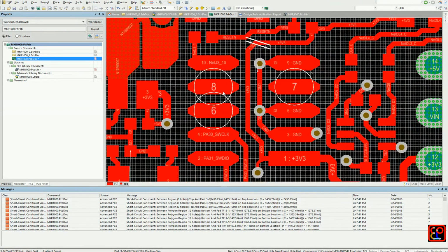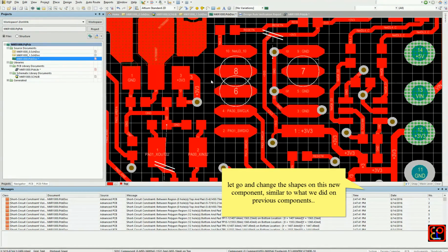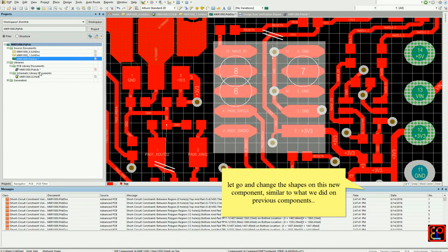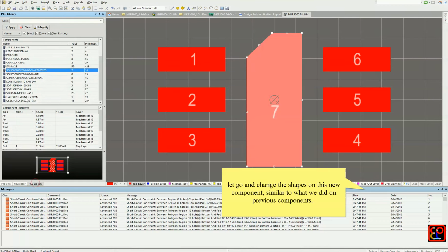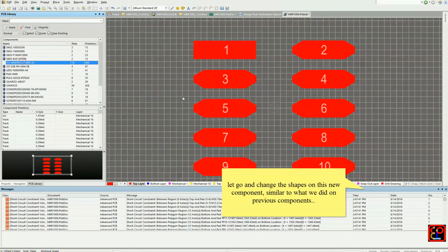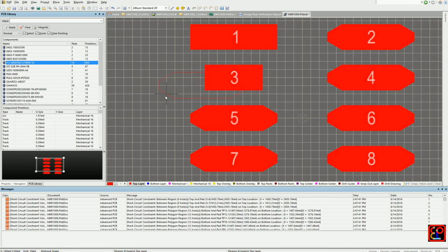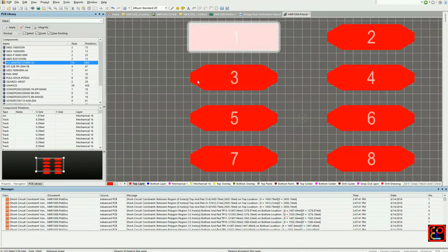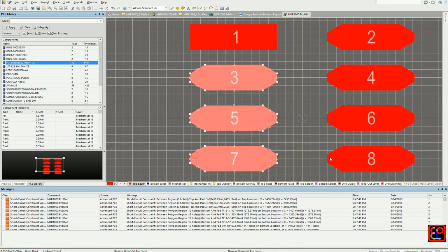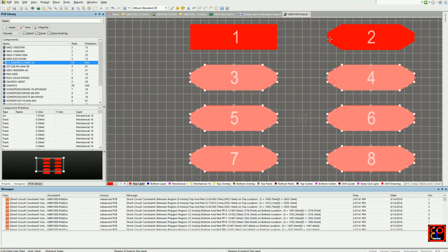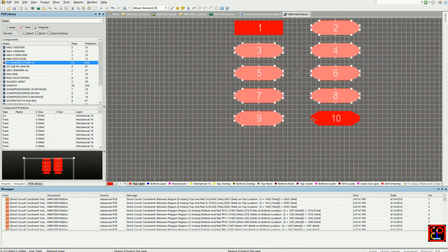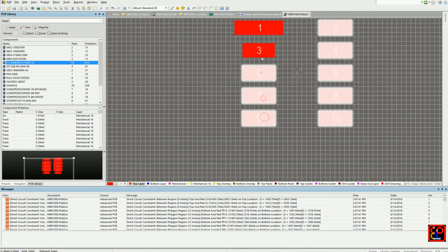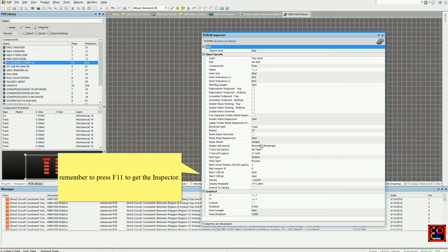In this case, it is showing an error on that footprint. Let's get the footprint name and open the footprint. In that case, you see another shape over the pad. Click on all the shapes, delete them, select the remaining shapes and click F11.